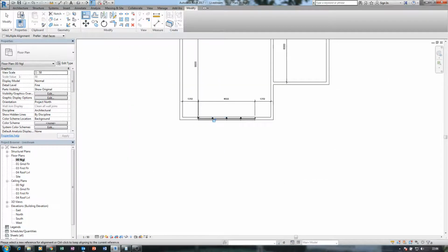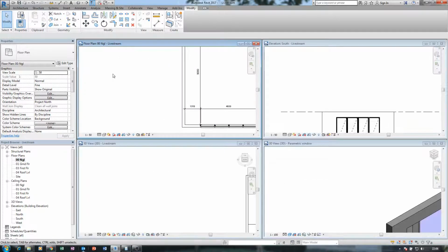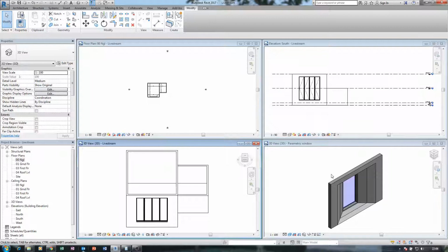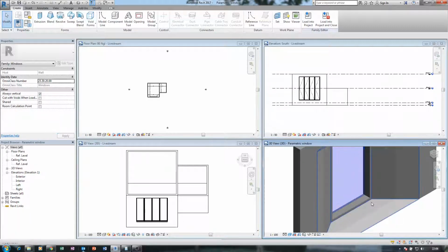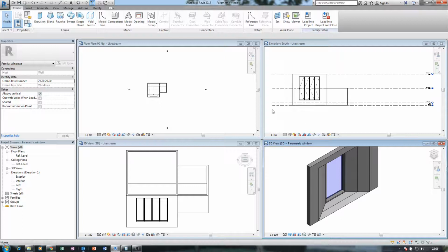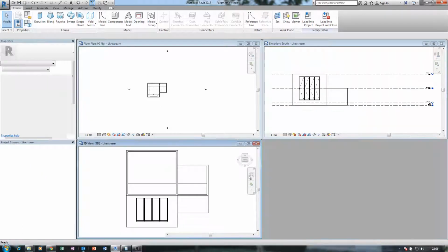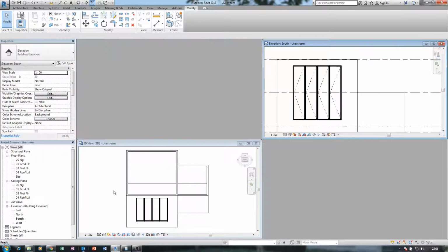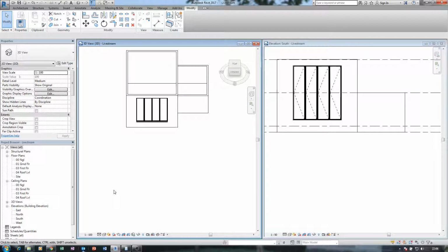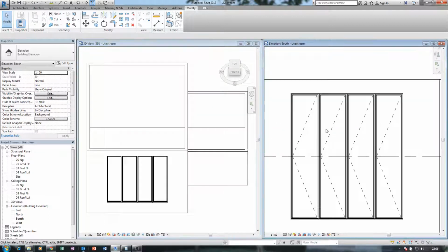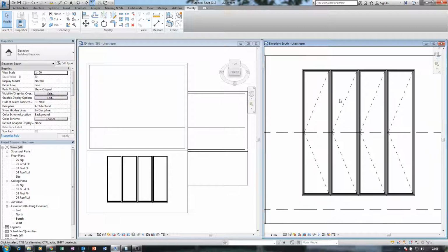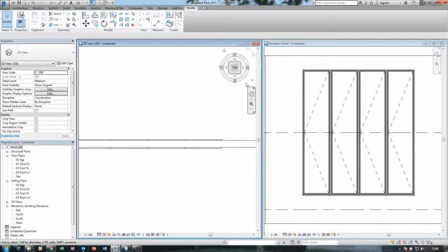If I'm right, good. So basically WT on your keyboard should give you all this, and pressing Z on your keyboard should be okay. This is the window I was making, and that's what was giving me problems, so I'm going to close it now. Later I'm going to get back to it. I can close the floor plan, press WT again, press Z, enter, so to have everything zoomed together. And if I'm making 2D, then I'm going to be concerned with all these. I'm going to make sure that everything works the way I want.